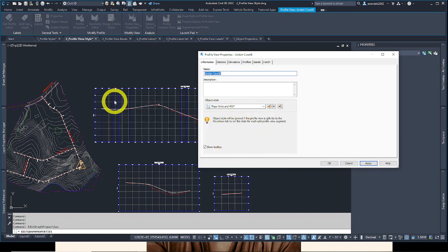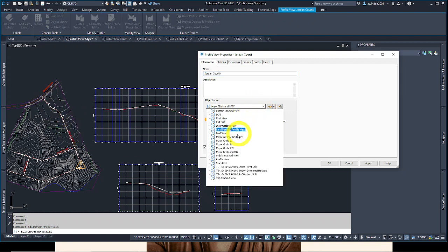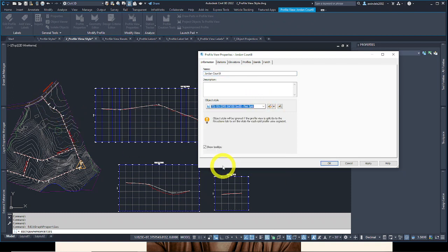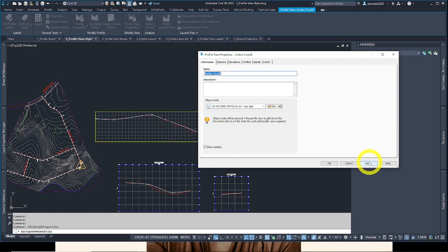These ones have horizontal geometry points. They signal where this curve here on the alignment starts matches where it matches on the profile. This helps us merge vertical with horizontal as we flip this alignment 90 degrees in the Z dimension, or elevation dimension. We can see better. This helps us with designing where our vertical curves are matching our horizontal curves over here. Okay, so there's different styles for different applications.